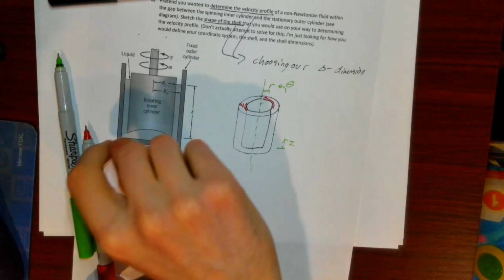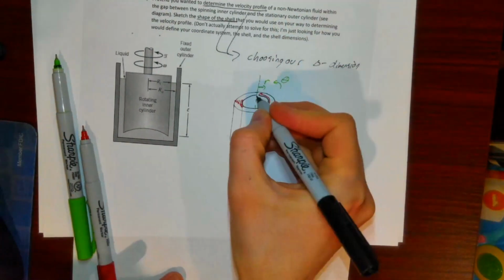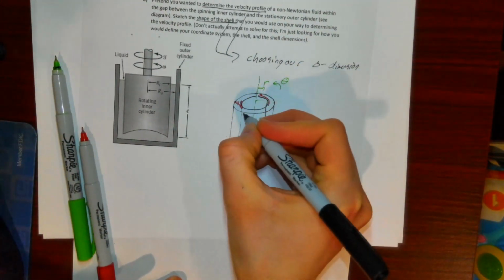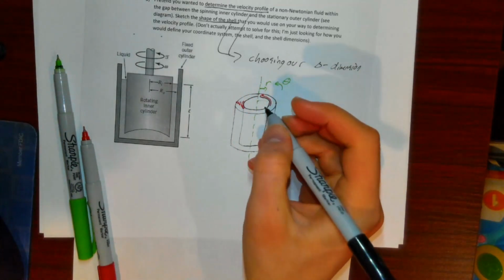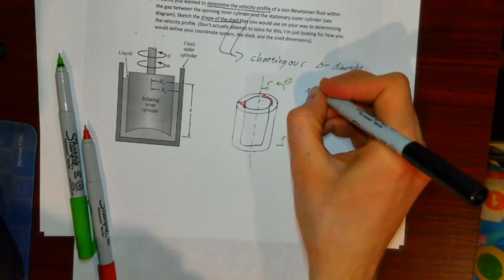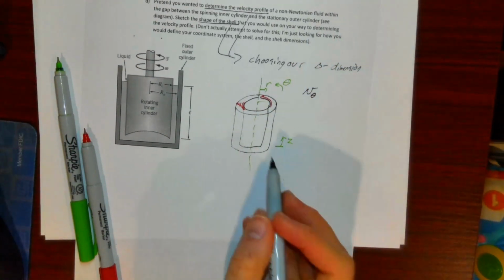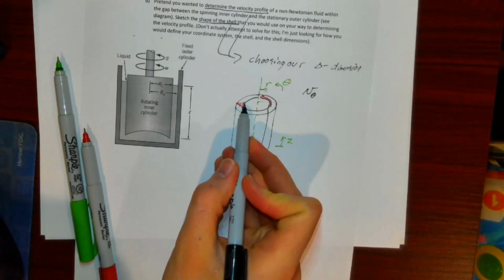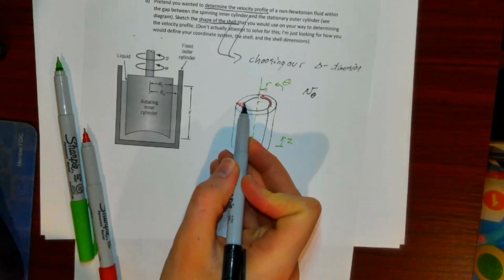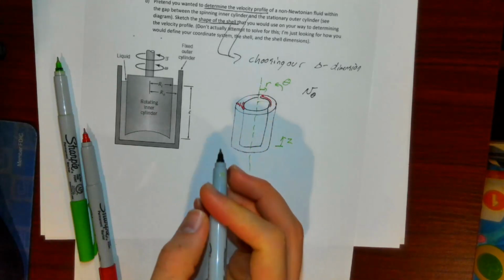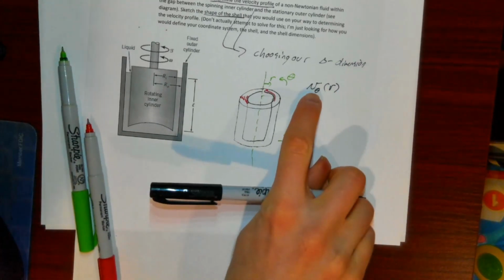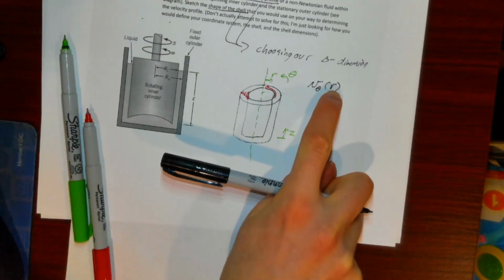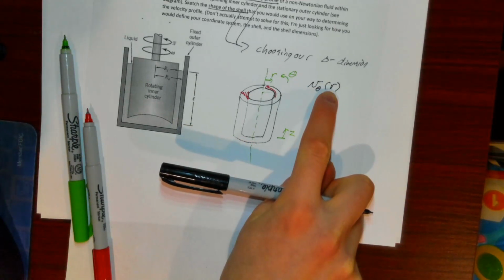So in what direction are we going to have velocities? Well, the fluid particles are essentially just going to be traveling around in little circles, following points on the cylinder that are moving around in little circles. So we're going to have a v in the theta direction. With the rationale that the fluid particles close to the inner cylinder are moving at some velocity and the fluid particles close to the edge aren't moving at all, we would anticipate velocity being a function of r. So we have velocity in the theta direction, which is a function of r.